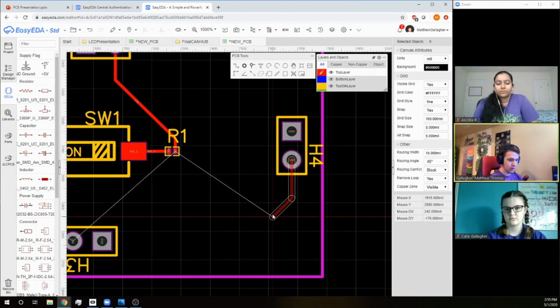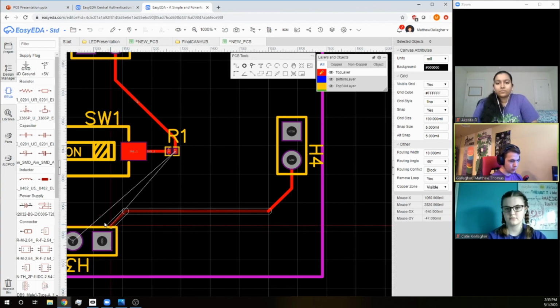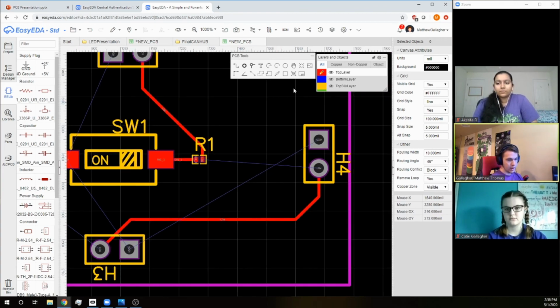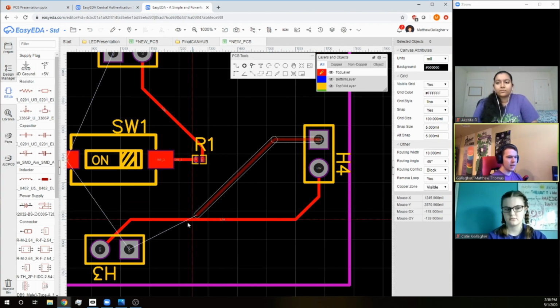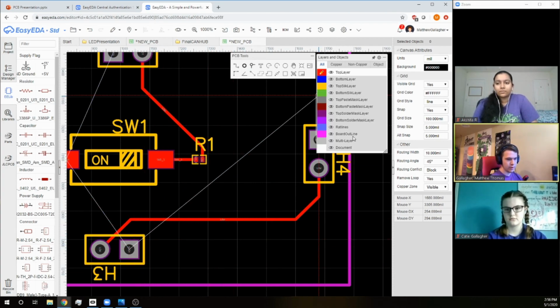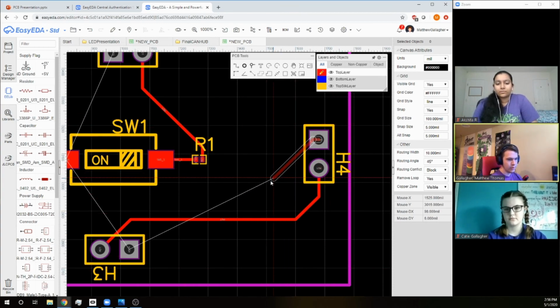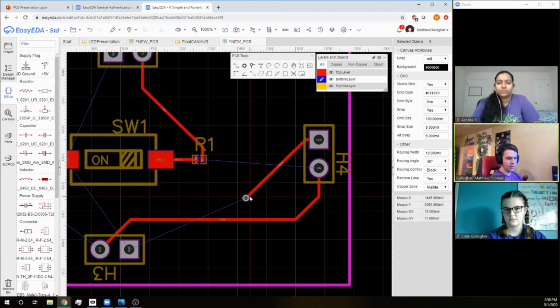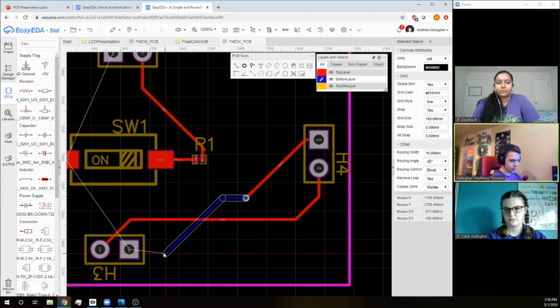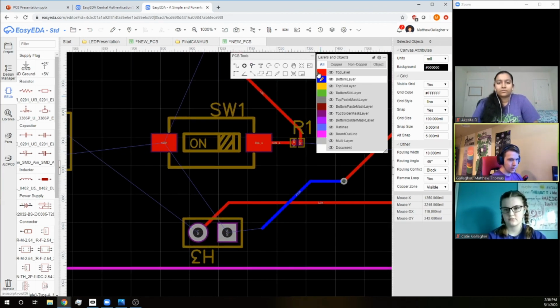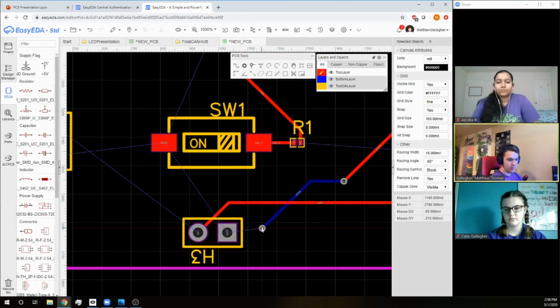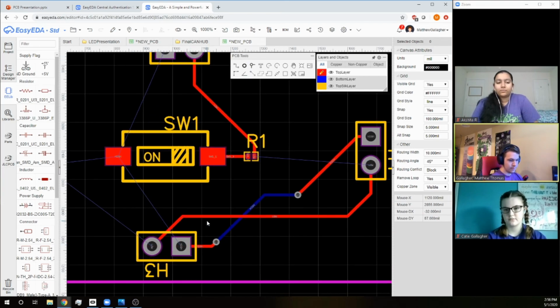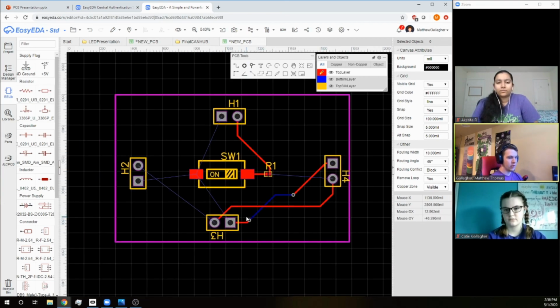So let's connect the low to the low. And getting a similar issue to when Katie was telling you about vias, we can't really cross over here, and it's going to look really gross if we go all the way around. So let's bring it out to here. We'll stop it there, grab a via, and then let's go edit the bottom layer. You can see the silk layer, or the yellow, disappear or gets darker. We'll bring this layer over a little. We'll go back to the top, add a via, and then finish off the connection. And there we go, we've chained two together.